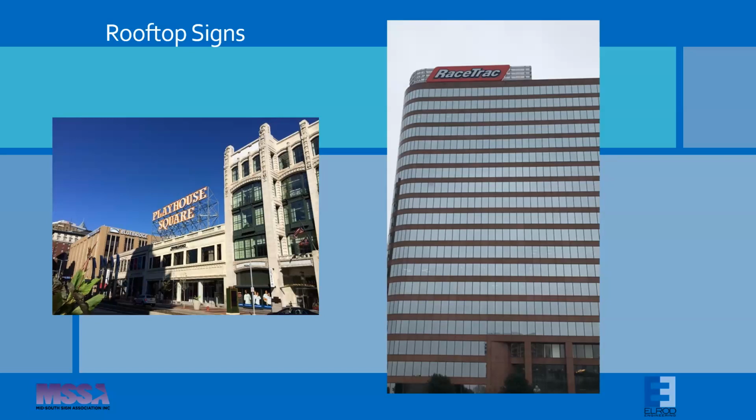It's important to get the building engineer of record involved for these designs. Your sign engineer can design the sign frame, that structure itself, but the connection of the sign and the frame to the roof should at least be coordinated with the building engineer, if not performed entirely by them. Kind of the way I describe it to clients.